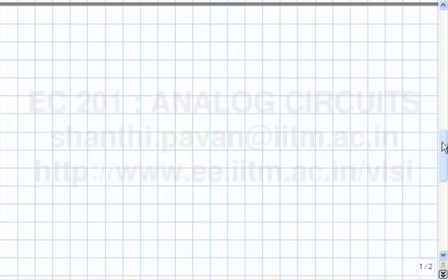And in the last two classes, we have basically gone through with the PMOS transistor what we did with the NMOS device. So instantly the number of circuits you know has gone up by a factor of 2. So we figured out NMOS, we figured out PMOS. The next thing is to do what? Figure out the two together. As a motivation for that discussion, let's consider a common source PMOS amplifier.